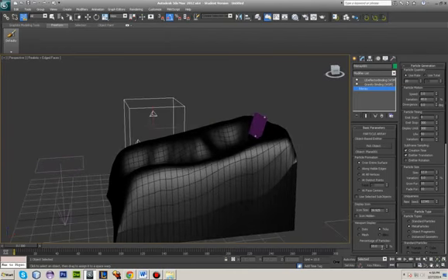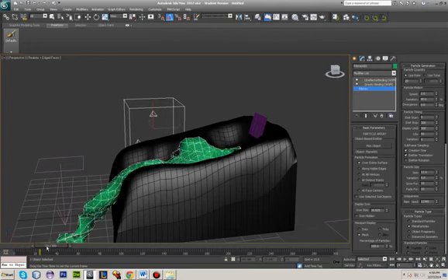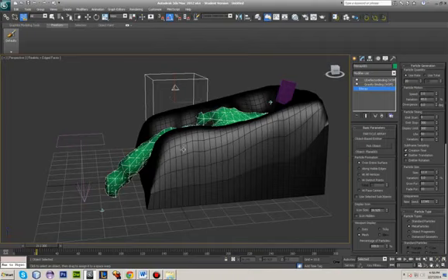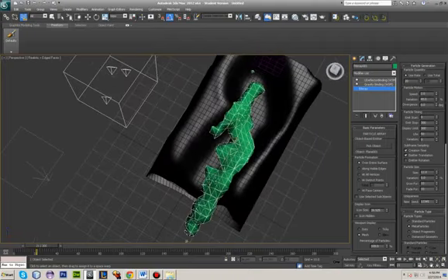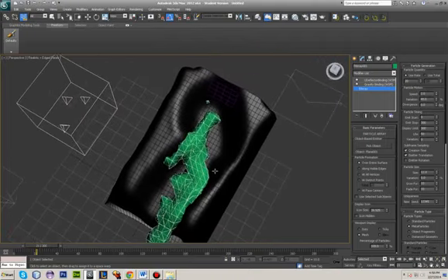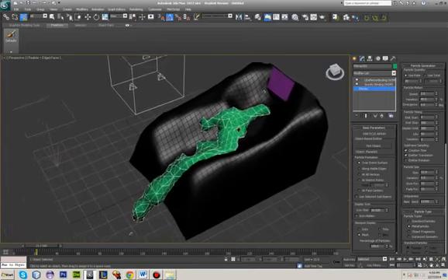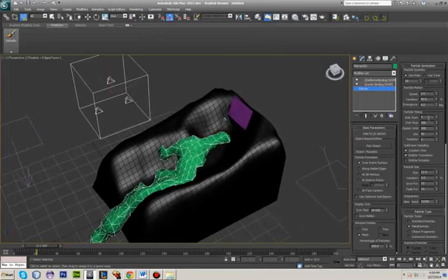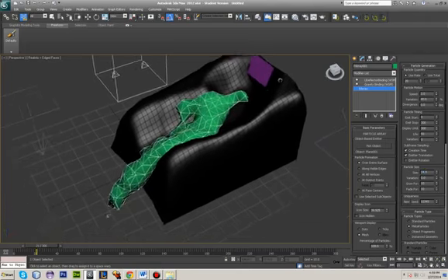I think if I go to 100% again and look at mesh, I may want to increase the size of particles. Let's leave that at 20 and see. Okay, so you can see some gaps around, so I want to change the size. I'll go to 14 and see how that looks. That looks a little bit better.